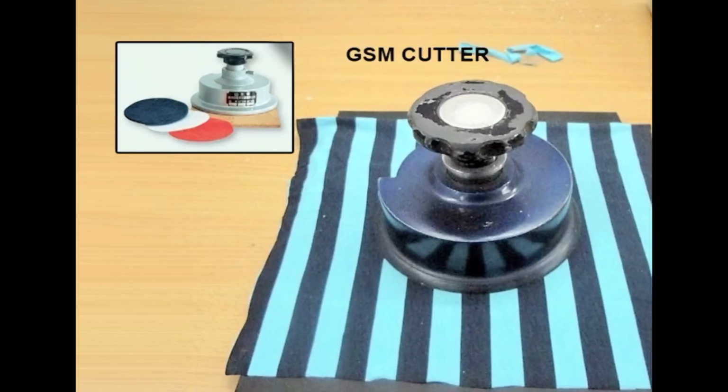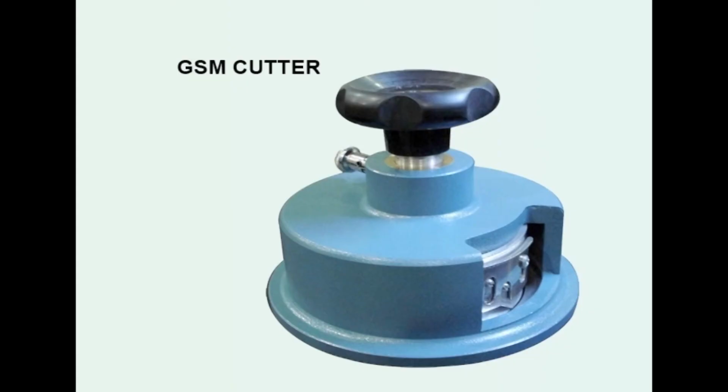The modern testing tools available today provide a GSM cutter, which is a template for cutting a fabric specimen, the weight of which is proportional to the grams per square meter. The common term used in industries is GSM rather than fabric weight. This facilitates easy comparison between the fabrics. It is very important in the case of knitted fabrics rather than woven fabrics.